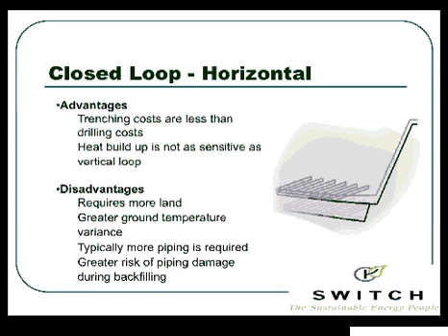More piping is required because we do have that temperature variation. When I go vertically, I'm at a stable temperature. You hit that magic 55-degree earth temperature, 55 degrees Fahrenheit, and it stays constant. It's the same temperature whether we're at 100 feet or 200 feet down.